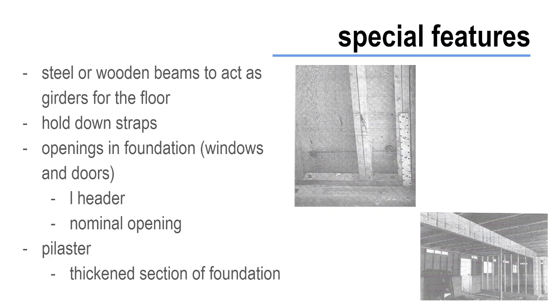It's important to get the masonry opening to the size of the window manufactured before forming the opening in the foundation wall. The opening has to accommodate the window, and it has to be the nominal size. That's why in our foundation plans we measure them from edge to edge.